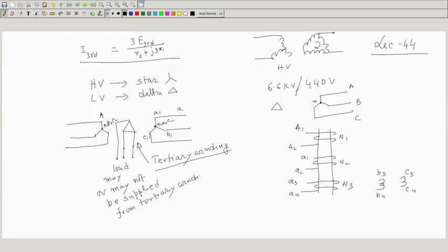I think you have got the idea. So, high voltage star, okay. Then delta, since I was telling you, it is always better to have a delta connection somewhere, and all these windings are wound on the same magnetic circuit. Like A phase, you have B phase, C phase like here. So, B1 B2, here also small b1 b2 and C1 C2, small c1 c2 and then C3 C4.